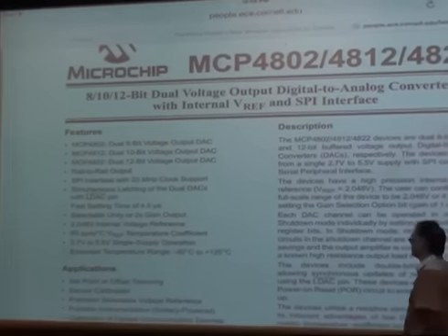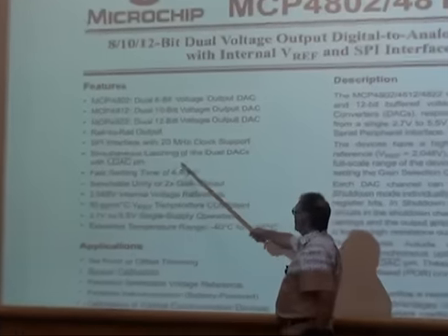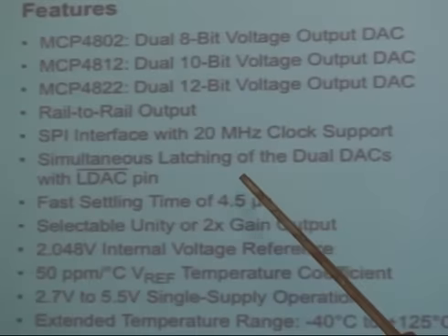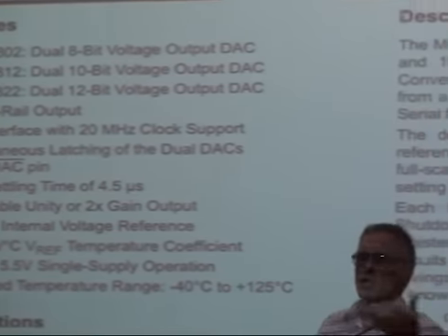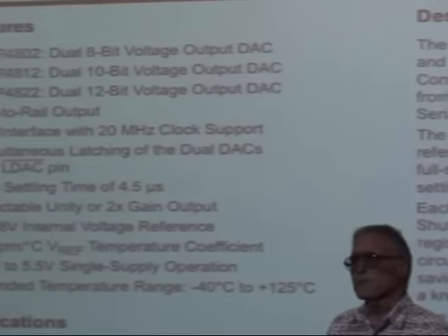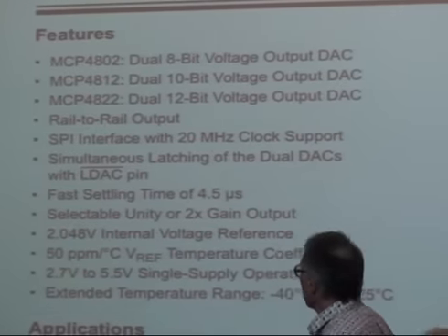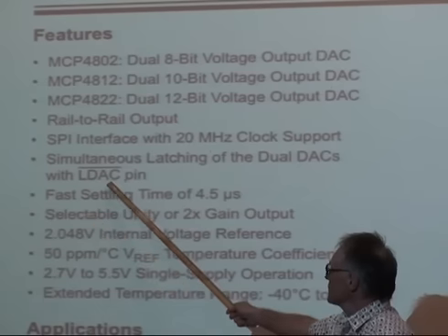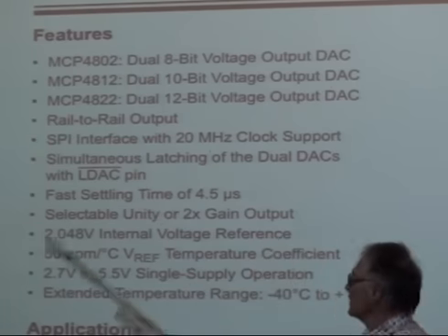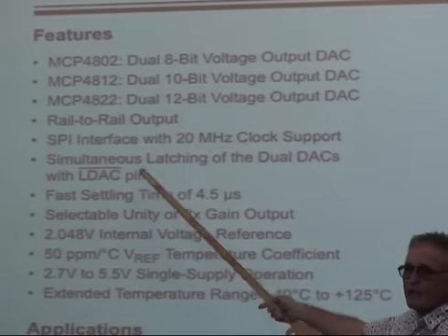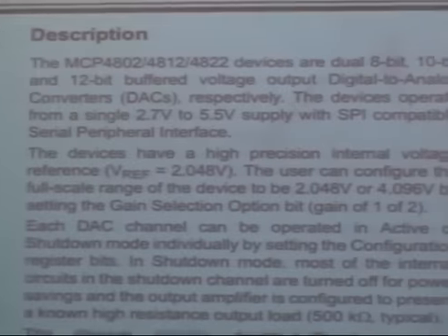Underline it. You have to load channel 1 of the DAC, then channel 2 of the DAC separately. Each transaction is 16 bits. It would be nice for some applications to have both voltages appear at the same instant on the output pins. You can do that by strobing the LDAC pin, but what we're going to do is just lock LDAC low.